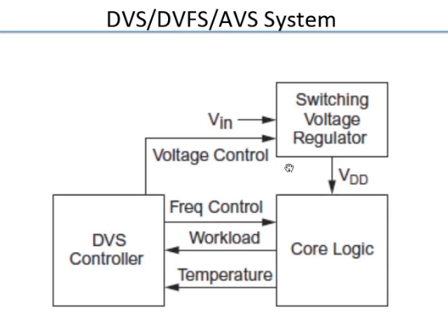And then there's of course this question which we had also alluded to in the earlier class. How do you figure out when to make these changes? When to change these different modes? One is under the control of the software. Maybe the programmer says now I'm going into low power mode, or it's an automated system which is continuously observing, and then it says okay, nothing much is happening, so let me dial it down. So there are two possible ways of doing this, and maybe a combination of both could also be done.